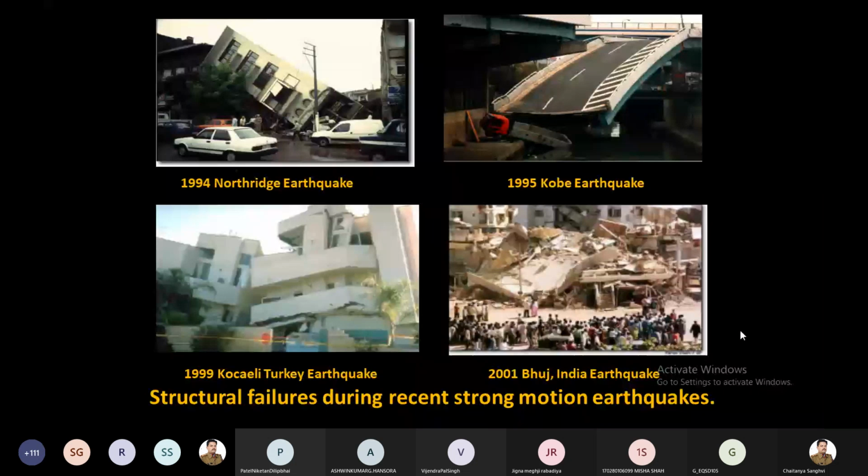Safe in a way that it is not going to collapse. Your structure may observe damage. Your structure may enter the inelastic region, but your structure remains safe. It is not going to collapse during the earthquake, right? So this is a real challenge. You see, when we design our structure for dead load and live load, we are using a factor of safety of 1.5. So for dead load and live load, the actual load coming on the column is 100, and we are designing for 150.